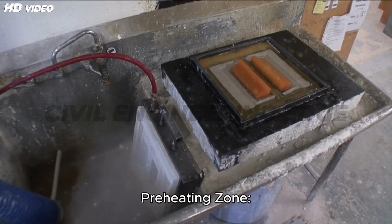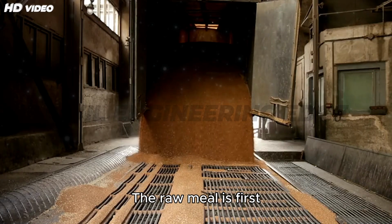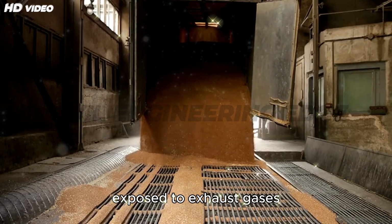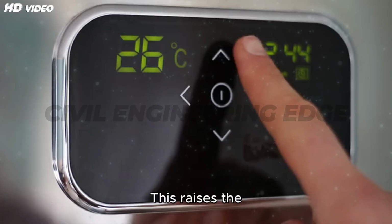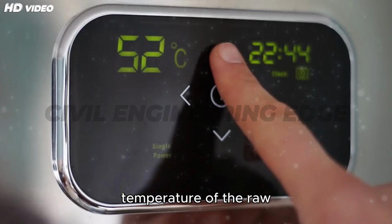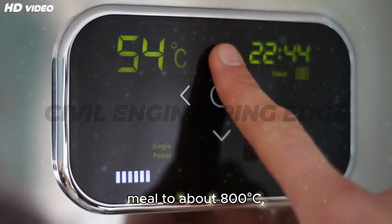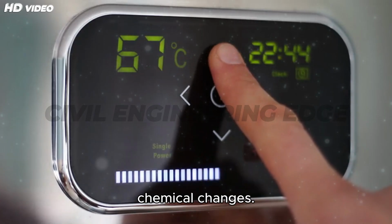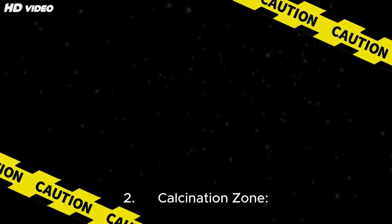1. Preheating zone. The raw meal is first passed through preheater cyclones, where it is exposed to exhaust gases from the kiln. This raises the temperature of the raw meal to about 800 degrees Celsius, removing moisture and preparing it for chemical changes. 2. Calcination zone.